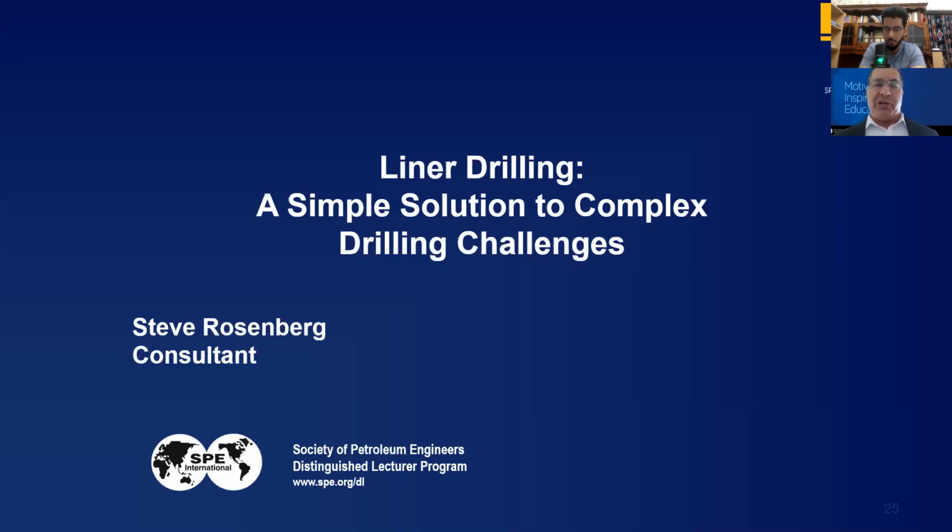You're ready to cement right away. You can model these non-retrievable systems to give a slight build or drop. That's ideal if all you want to do is maintain the established tangent angle or verticality. It's a lot simpler, a whole lot cheaper, and a lot less things can go wrong.